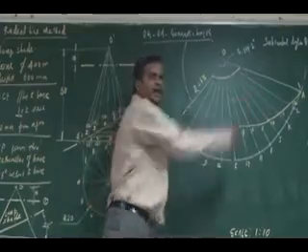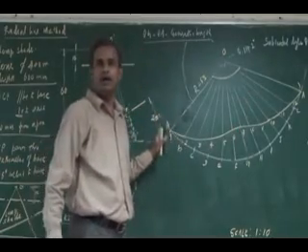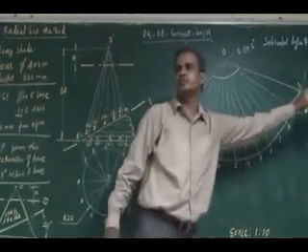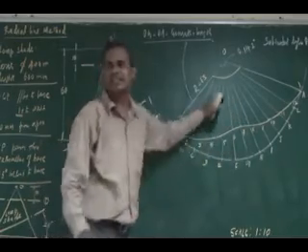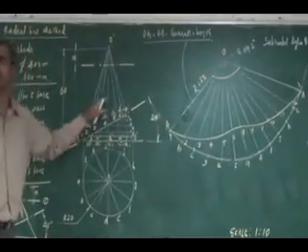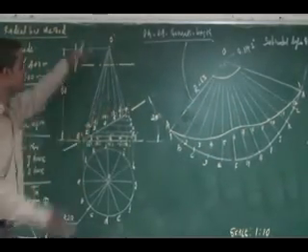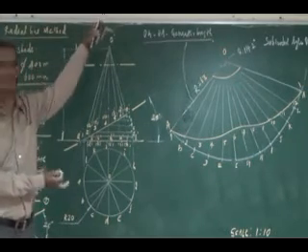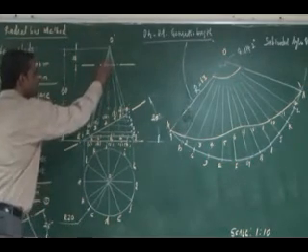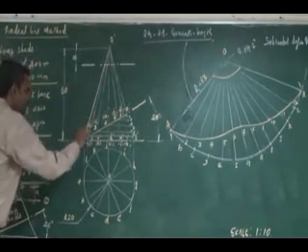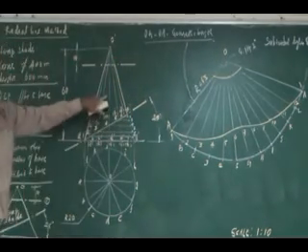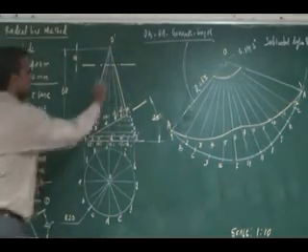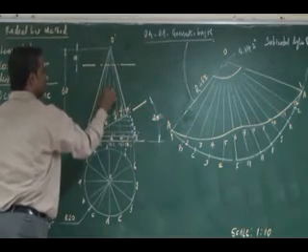So this is the thing. Cutting points I have joined as a smooth curve here in my development. Then, which is the lampshade portion? In between these two cutting planes, this portion is my lampshade. In my front view, this portion is my lampshade.